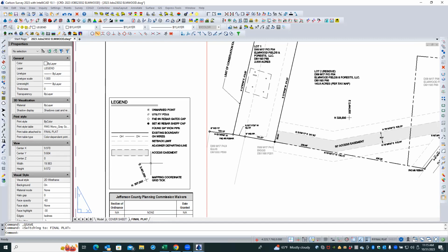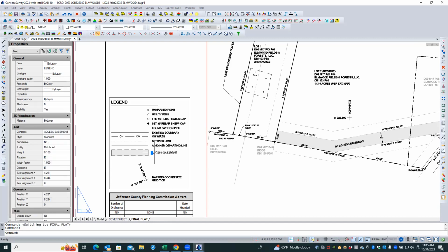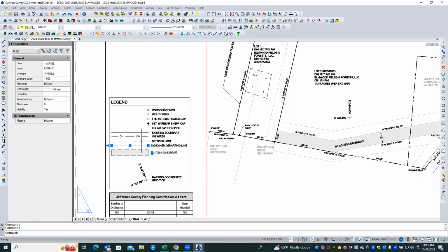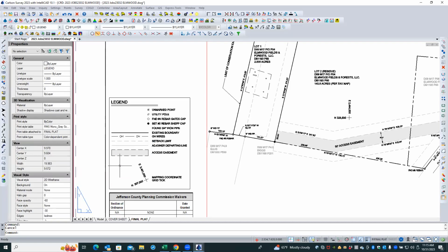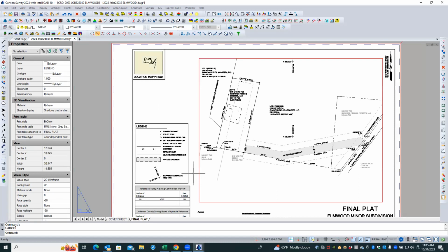And there's a couple of ways of doing this. So right now, if I look at these things over here, I see they are all in paper space. So we can do that same thing as we can recreate that legend and put it over here into paper space, or we can make a new viewport and look into the model space and keep it there.